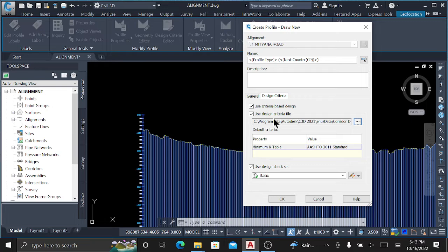Okay. However, what this tells us, once you activate the design criterion, the feature that it only allows you to see is that it can warn you once you've violated some variable or parameters. For example, if you have the curve being very short, it doesn't allow for a minimum set distance to be achieved, or it violates a certain value of k, right? So it will be able to show you the warning error. That is the only way. But once I remove that, that means that the warning errors won't be visible, but my drawing of my curves won't be affected. Either way.